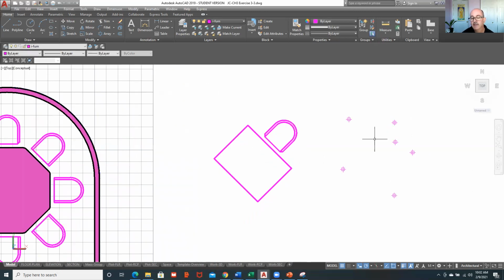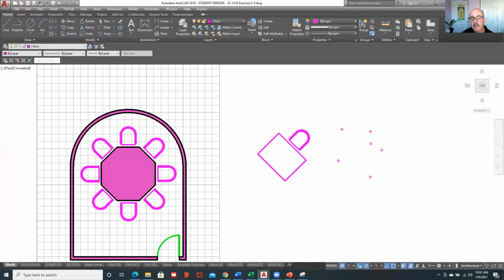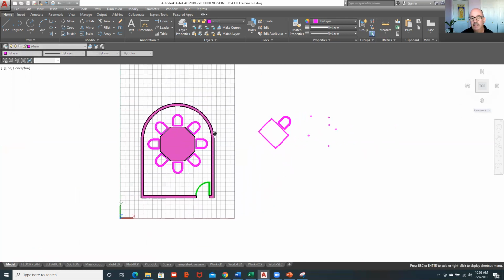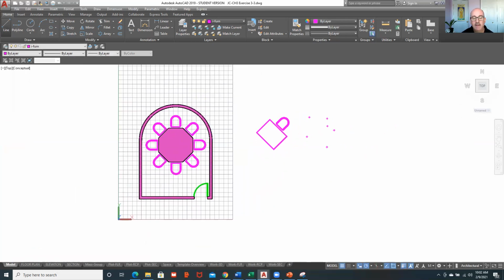And I'll use point styles to locate things. Like if I'm putting in a fence and I go down to Home Depot, fence is sold in 8-foot sections. And so you can use commands like divide and measure to place points along a line. So if I have a line here that's going to be like a fence, and so we'll make it 40 feet long. And then if I wanted to put fence units on it, what I would do is I would say measure. And so they have divide and they have measure.